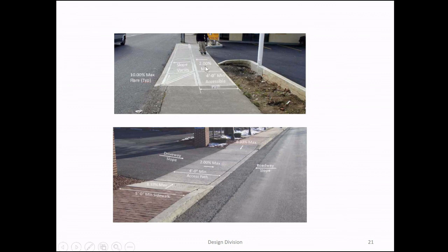And so when you design driveways, it's minimum 2% and a 4-foot pathway minimum. We have a template that we use to make sure that this point here will not scrape when the vehicles go up here. So if you run that template and this point scrapes, then you're going to have to depress this driveway, and you're going to have to go back and reconstruct on private property.